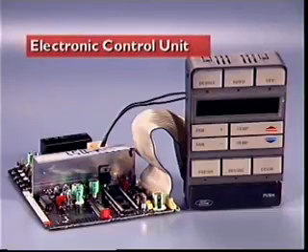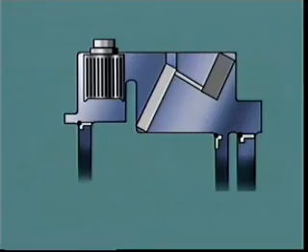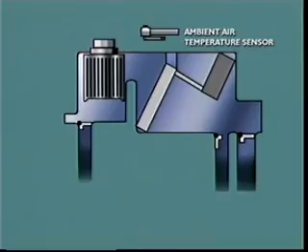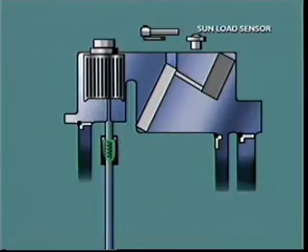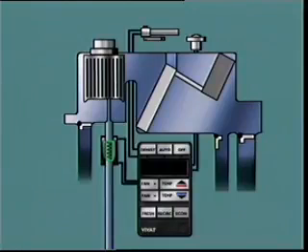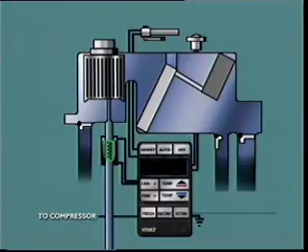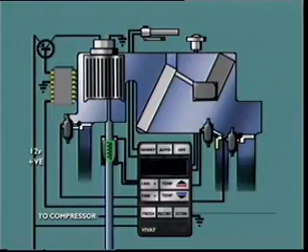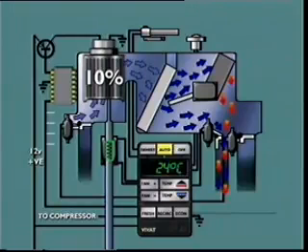This section examines the electronic control unit for automatic air conditioning systems. An automatic air conditioner is a manual air conditioner and heating system equipped with sensors which detect changes in ambient temperature, cabin temperature, and solar radiation. The electronic control unit evaluates the signals from the sensors to determine the operating conditions, and outputs actuators to move dampers and valves to control the throughput, temperature, and direction of the air delivered by the system.